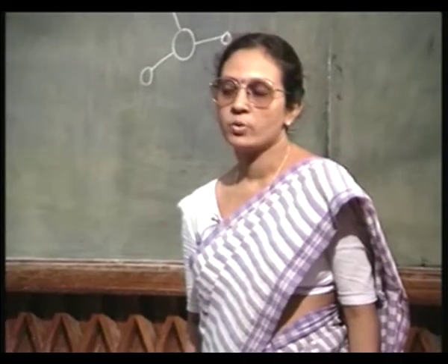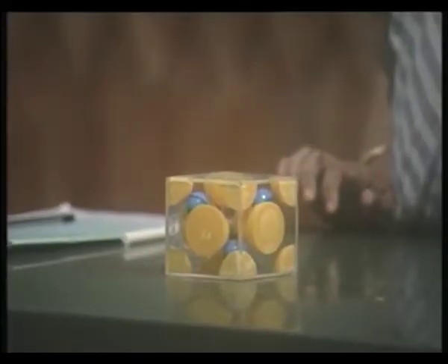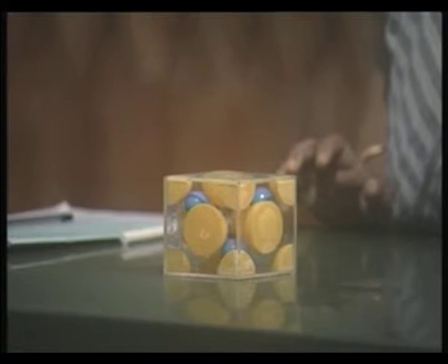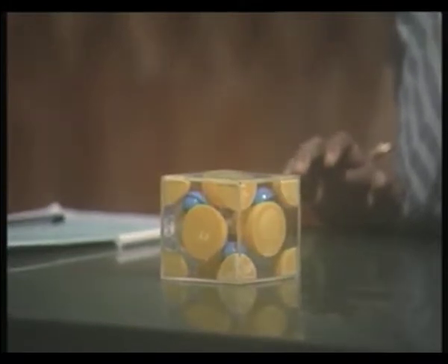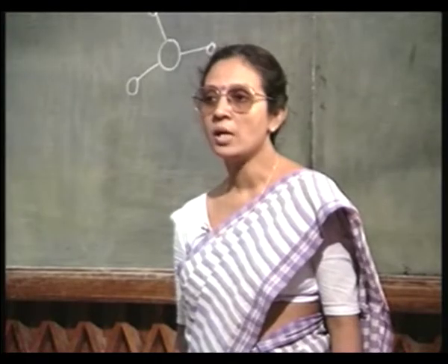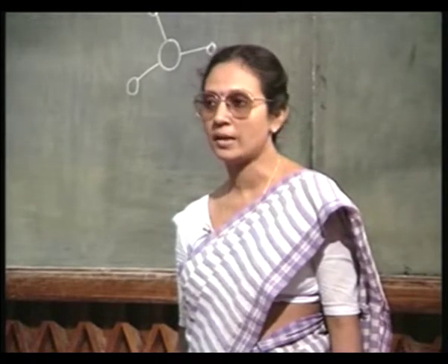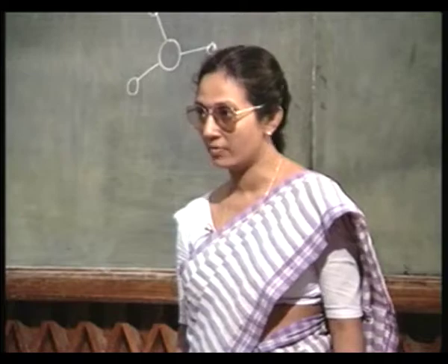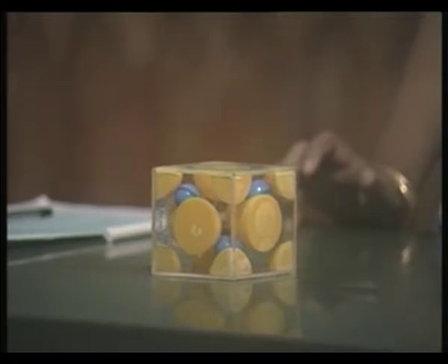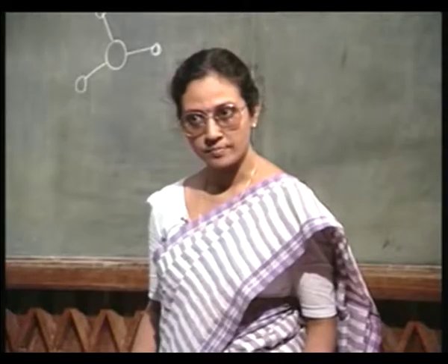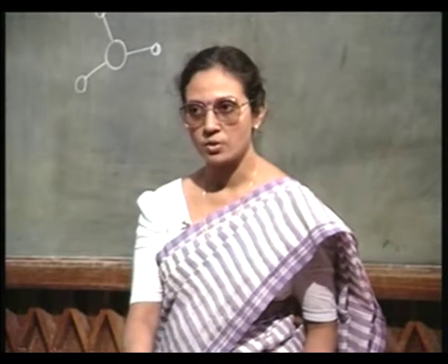You remember, we said that a diamond lattice or a zinc blende structure is quite loosely packed. The packing density is only 34% compared to an FCC lattice, where the packing density is quite high, greater than 70%. So, the packing density of a zinc blende structure is low. That means there is a lot of empty space within the crystal. Where are these empty spaces located?